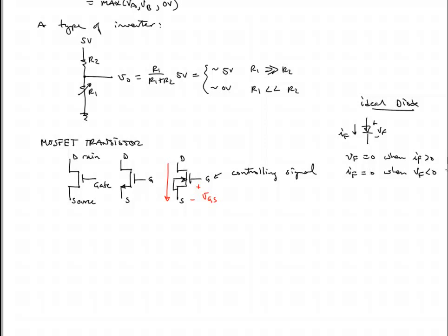From further study of the diode, we can model that as a constant voltage drop diode. We can add a resistance in series with it to have a constant slope model, and then we can recognize that there's a Shockley exponential equation that describes the current and voltage relationship. Finally, we acknowledge that a real diode will also have some ohmic resistance, so you have the Shockley equation plus some series resistance. That's a fairly decent basic model for a diode. Well, we're going to do the same thing for the MOSFET.